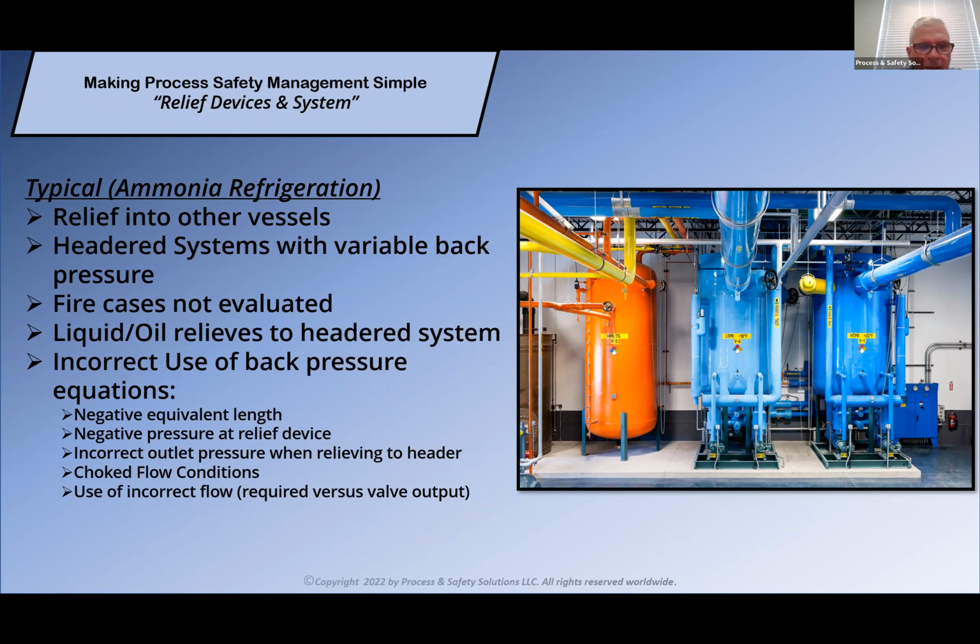Headered systems have variable back pressure. We see this quite often where you have multiple relief valves relieving into the header, but there was no consideration given for the fact that you could have multiple relief valves relieving at the same time, affecting how other relief valves in that system can relieve as well.